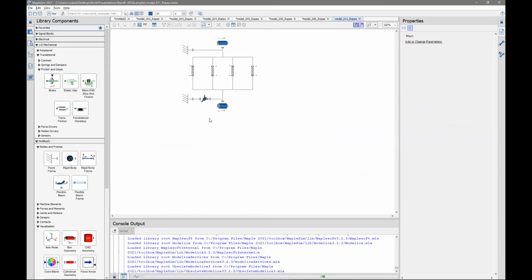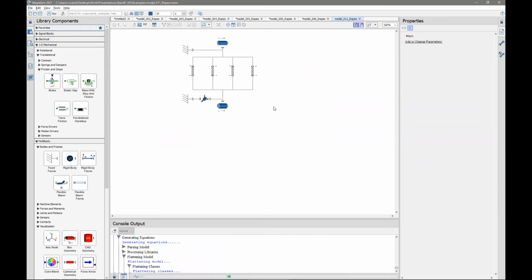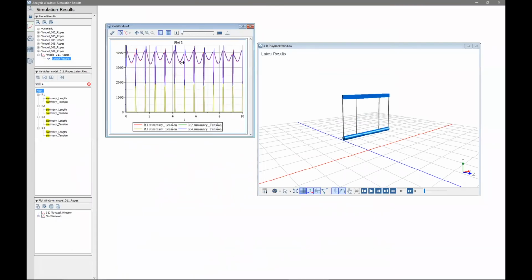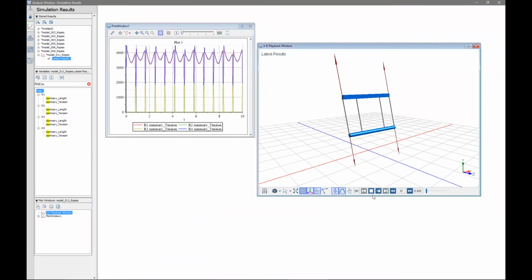As you will see, if you have 4 parallel ropes between 2 objects, and the objects are rotating, the ropes will not see the same tension. And from a design standpoint, that might not be the expected outcome. As you can see, the 2 outer ones are taking most of the load, but under certain angles we have almost a pulse-like tension going to the other 2. So how to fix that?